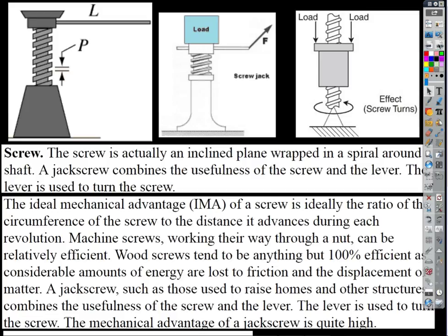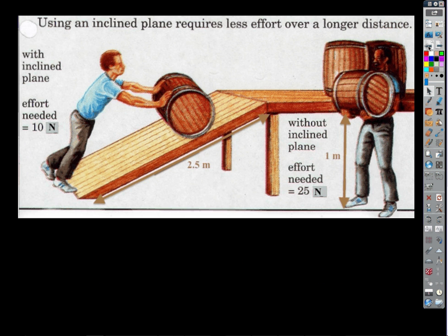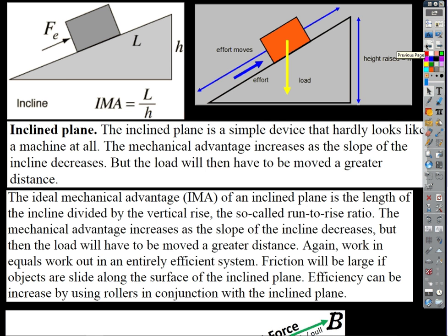Think what this does now. If I'm turning a screw, the threads are turning through a hole that's been bored out, right? So there's a positive and a negative pattern with the threads. When I turn this thing, those are just sliding past the grooves in the hole that's been drilled out of the material, right? So what's really happening there? Isn't that just the equivalent of sliding something up a ramp? Only the ramp has been wrapped around a core, right? You see what I'm getting at? Really, the ramp has been just wrapped around a core.